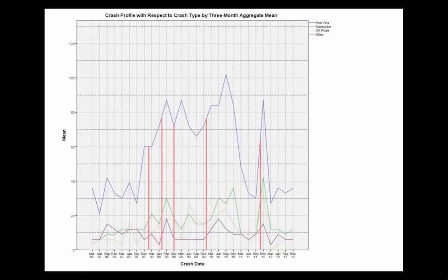And then my final analysis was just kind of looking at the crash types in particular. So rear ends and side swipes are the most common types of crashes, but especially because they were narrowing the general purpose lanes to accommodate for now 2 express lanes in each direction, I figured this extra sense of claustrophobia among drivers would increase, especially side swipes, not to mention rear ends.